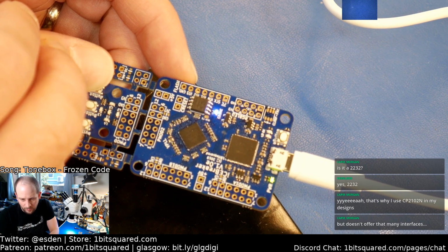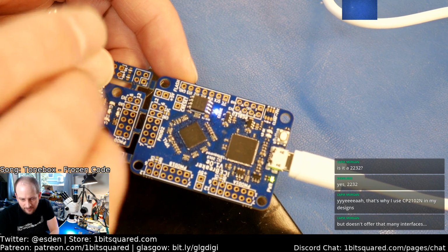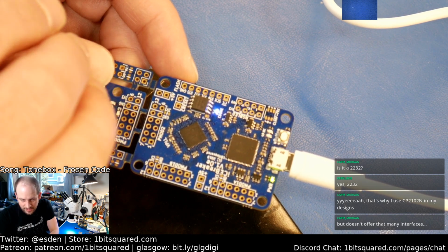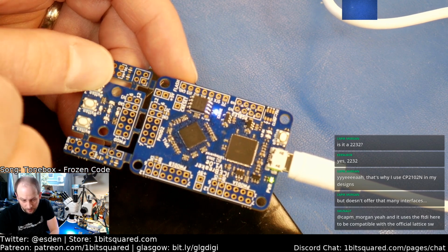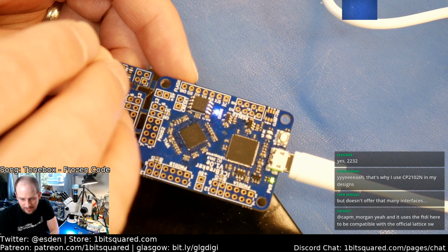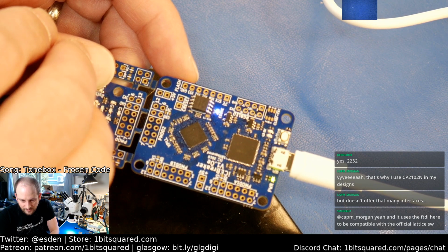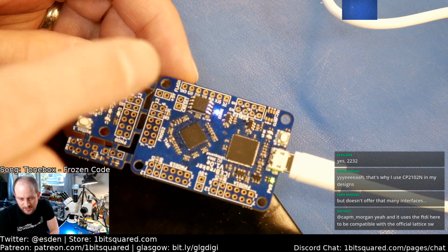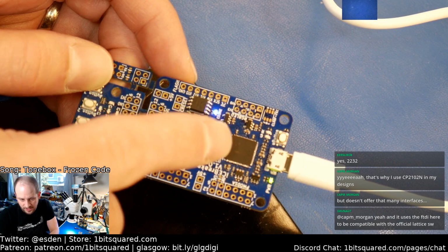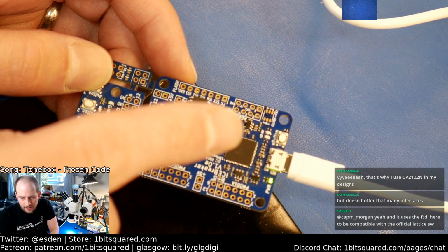Currently we still buy their chips. I'm really looking forward to removing that. The problem is that even the chips that exist, for example the CP2102, are too slow. It doesn't have the high-speed USB interface. And also, it is not compatible with the interface that FTDI has, so we cannot use it with the vendor tools.